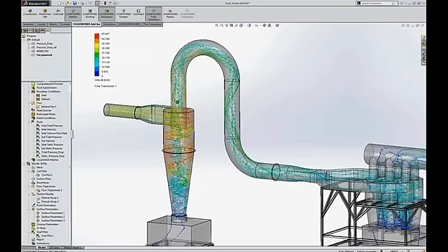And so it gives you very good results, and it makes it very easy for us to get large structures analyzed in very little time. So definitely. And you do have the option of still having solid parts in areas of concern. So let's say you've got a junction where multiple beams are coming together. You can still represent that as a solid geometry, so you can look at the stress through the 3D geometry and have beams for the rest of the structure. That works really well.